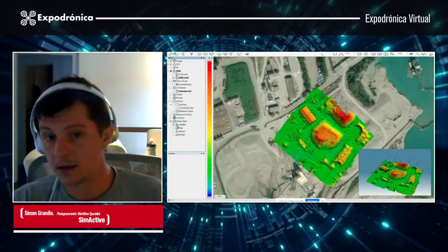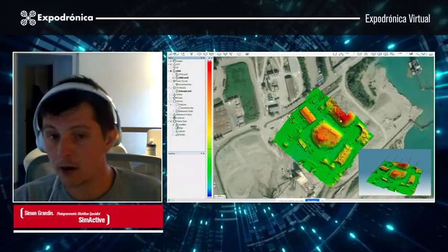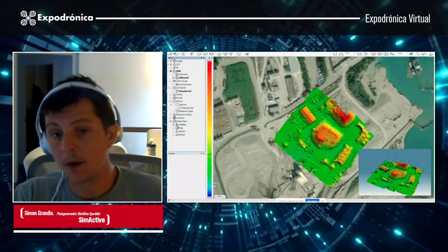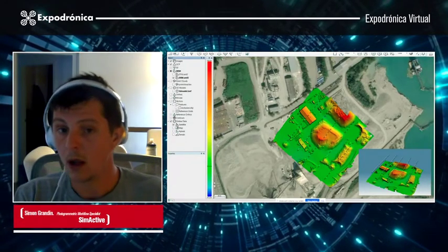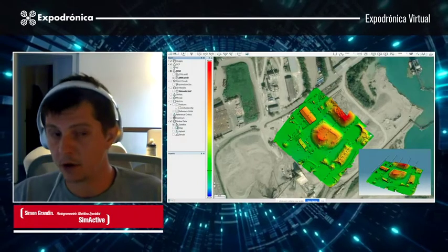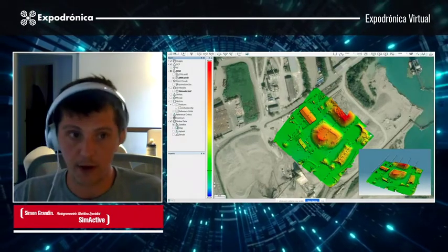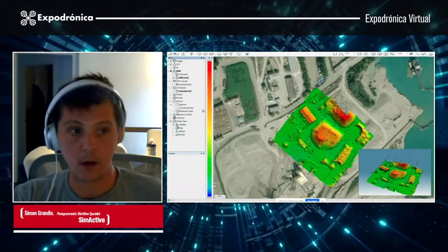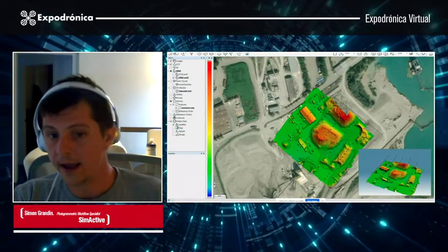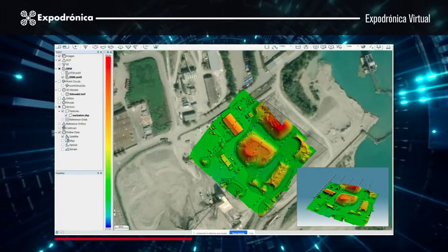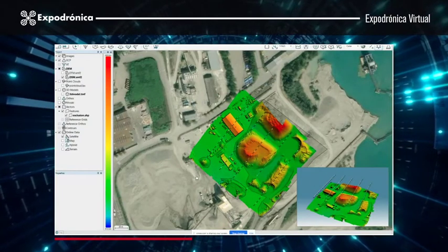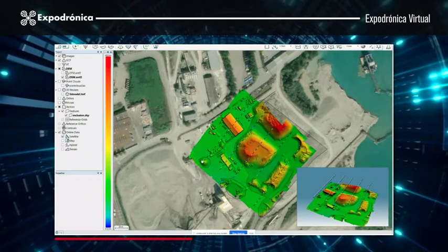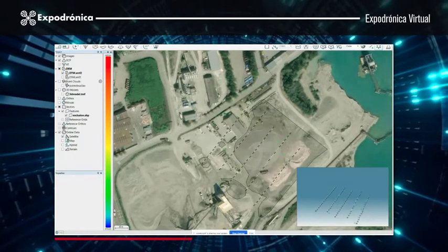From this surface model, some additions can be done. Let's say you want to keep the stockpile within your terrain model so you have better accuracy for your orthorectification. The user can create polygons as exclusion zones and use those polygons during the terrain model extraction, which will give you something like this.